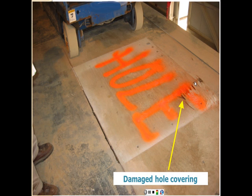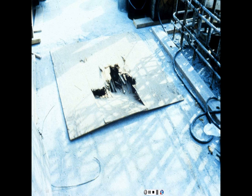And again, the cover here, although it's marked as hole and everything, it's plywood and it's damaged, so it definitely will not withstand twice the load that should be imposed on top of it. Same thing here, so this should be definitely replaced. Here the cover does not cover the whole area, so this is not going to work.